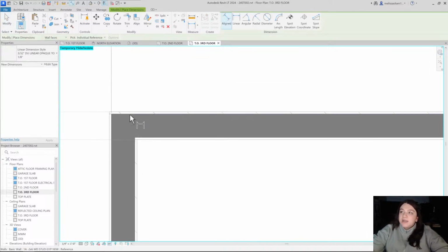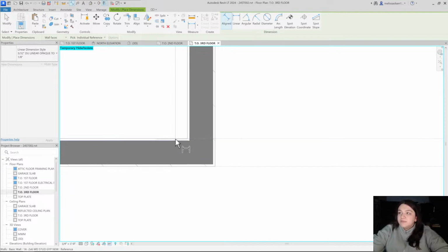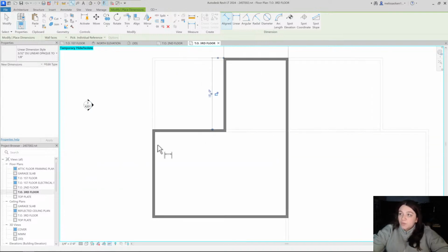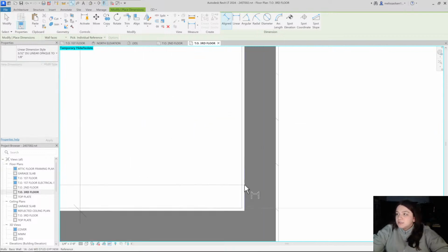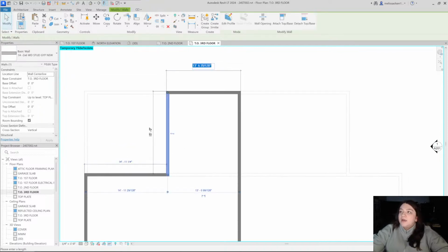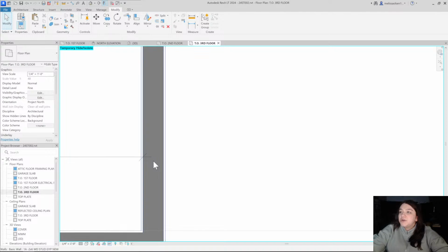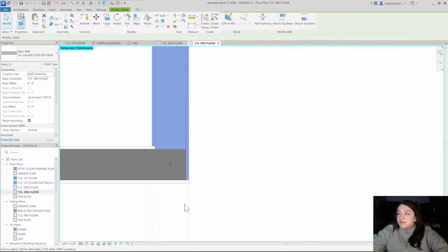So I will go in and dimension these walls really quick because they are new walls that we've laid down, and I just want to be extra sure that from stud to stud we're on whole numbers, because again, this is a brand new house. There's no reason things should be on weird fractions. So this is going to be 13.6. This is going to move over. Half of an inch is okay, where this is aligning to the wall below and this is also aligning to a wall below.